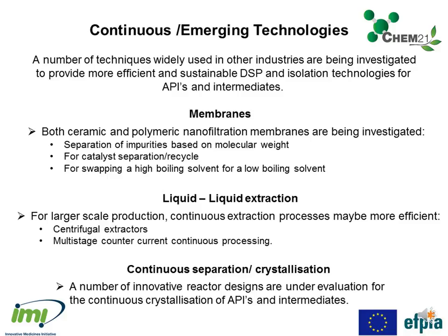Membranes, both ceramic and polymeric nanofiltration membranes, are being investigated for a range of tasks. So separation of impurities based on molecular weight, catalyst separation and recycle, and for swapping a high boiling solvent for a low boiling solvent, which is actually quite difficult to do via distillation.